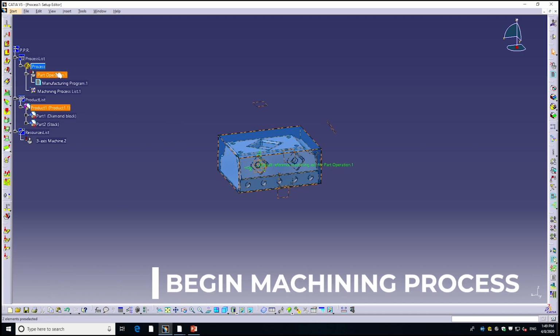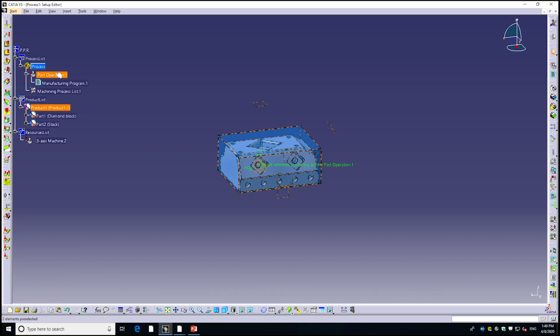In 3+2 machining, only 3 axes are coordinated at any time, and the tool axis remains fixed during machining. It is basically 2.5 and 3 axis operations, but the tool spindle is either rotated, tilted, or both.